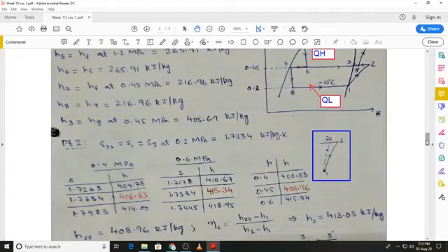The next thing that I have done is, by using the table, I've used the superheated property tables for refrigerant 134A, and we have to go to an intermediate pressure of 0.45. Now that pressure is not available in the superheated property tables, but we have pressures, one which is less than 0.45 and the other one which is greater than 0.45, which is 0.6 megapascals.